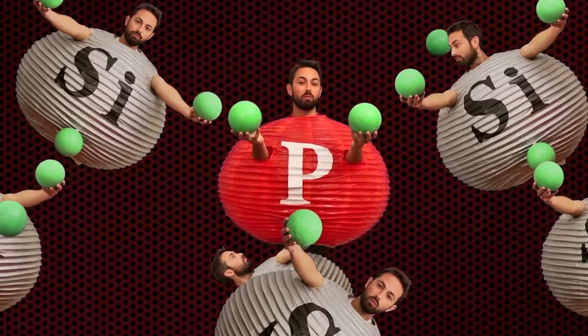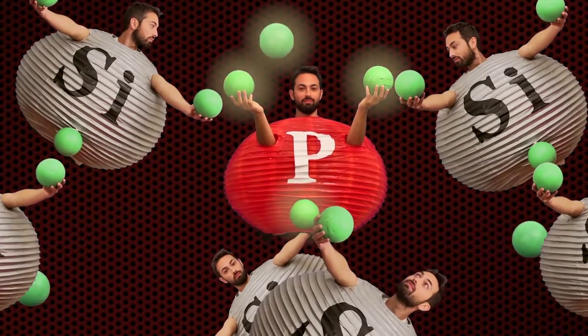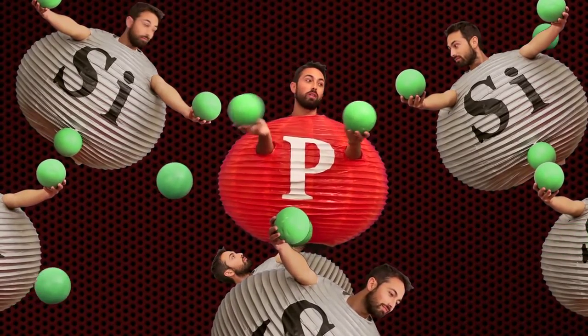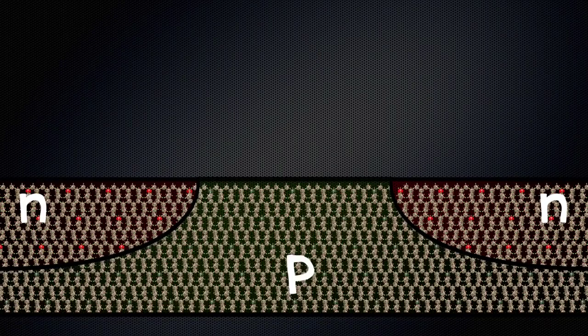Now, it's a common misconception that N-type semiconductors are negatively charged and P-type semiconductors are positively charged. That's not true. They are both neutral because they have the same number of electrons and protons inside them. The N and the P actually just refer to the sign of charge that can move within them. So in N-type, it's negative electrons which can move, and in P-type, it's a positive hole that moves. But they're both neutral. A transistor is made with both N-type and P-type semiconductors. A common configuration has N on the ends with P in the middle.